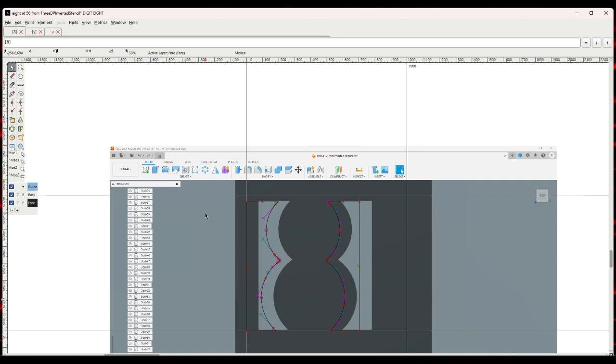When it's troubleshooting the letters, I experimented around with some of the tabs here. Whenever it troubleshoots the letters, it's looking for more than a certain number of points, something like 1,500, which is a lot of points. But at the same time, Fusion can handle a couple 10,000 polygons. When it's making a mesh, the things can have 10, 20,000 triangles, and it's just fine.